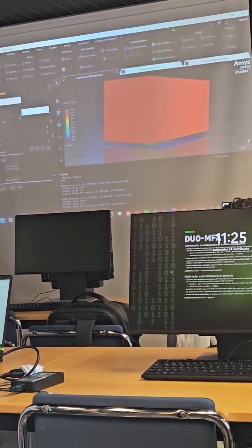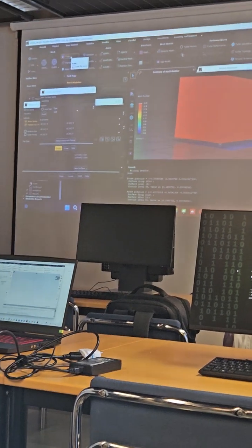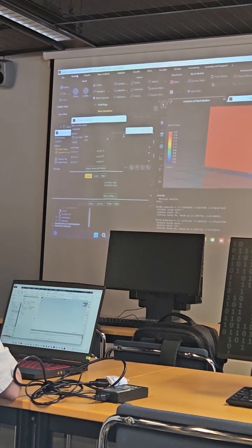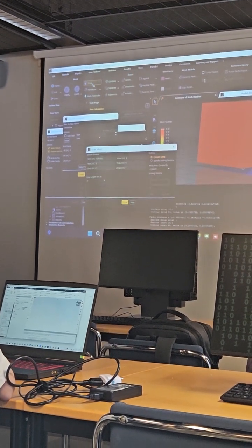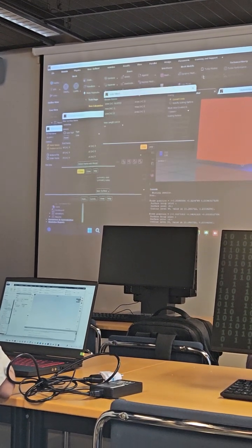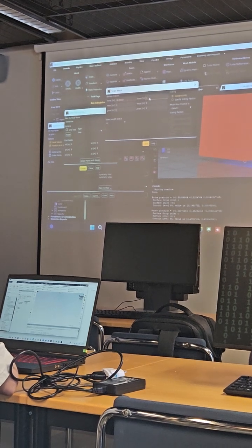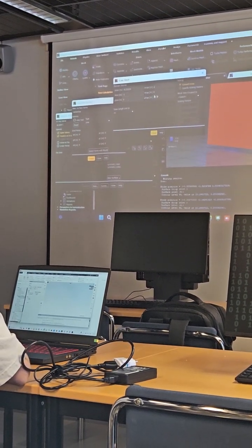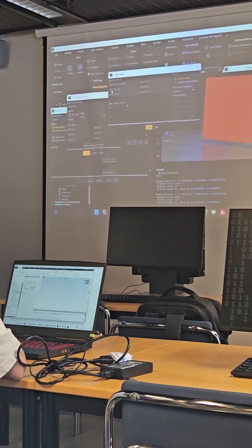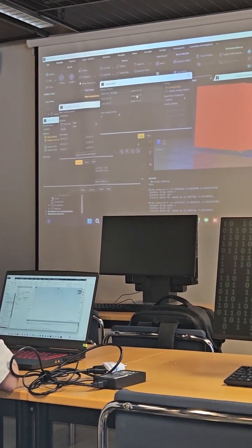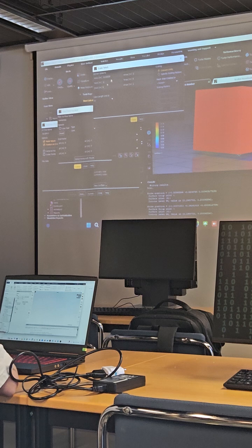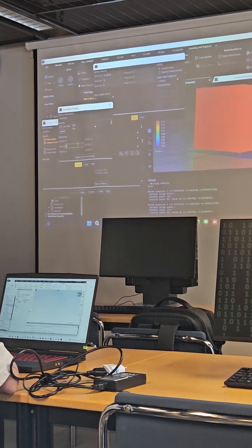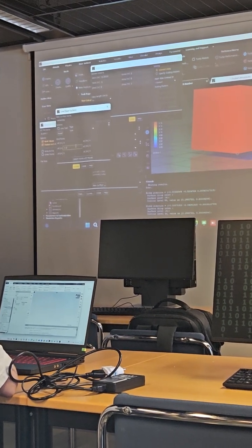You can find that in scale on the top here in the tab domain scale. So these are the minimum x, y, and z values of our domain extent. So the middle y in this case is minus 0.5. So we can set both y's as minus 0.5.